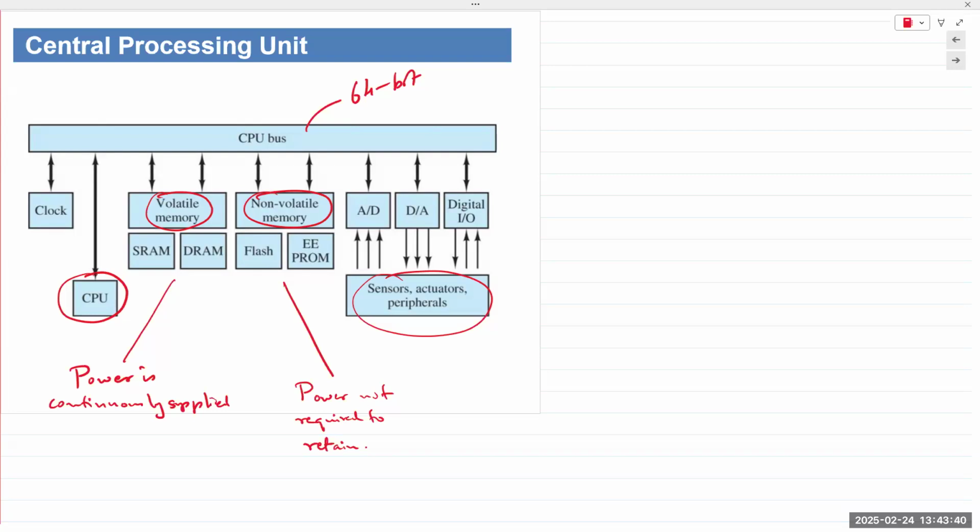The programming is done during manufacturing itself, meaning you program the chip in your fabrication process. It's only designed to do a few things. If you take multiple transistors and you create a circuit, you already programmed that circuit into the fabrication process to actually function as a switch, maybe to function as an amplifier. Does that make sense? So the function is itself designed into the circuit. Hence, read-only memory. Then they came up with programmable read-only memory, or PROM, meaning the consumer could buy the ROM and program it just once.